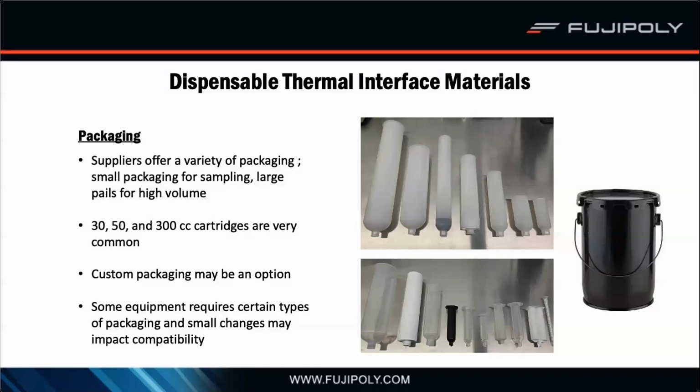That just helps ensure that the two components get mixed properly while they're being dispensed. But as you can see in these images, there's a wide variety of different cartridge sizes, styles, and dispensing tips. Many of these have different limitations on pressures, and of course there's compatibility with nozzle tips and threads.